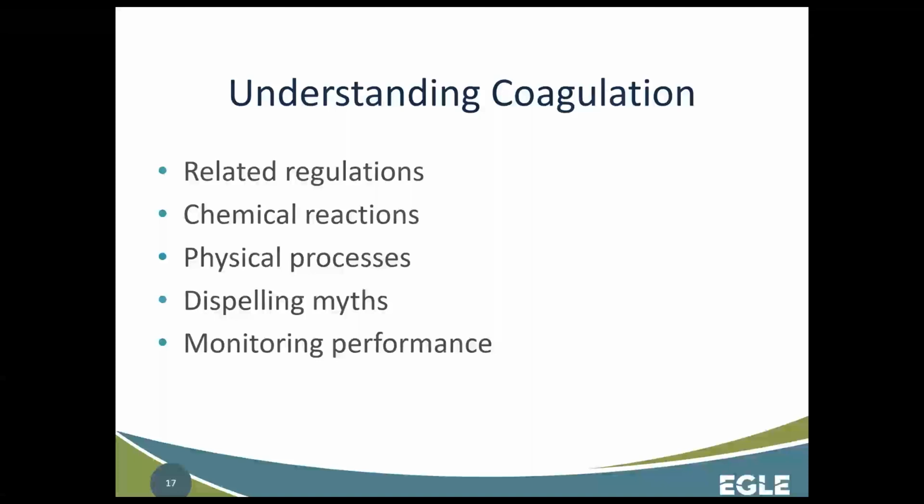Again, I never want to dismiss the ability of an operator to visually inspect a floc basin and to assess its performance. I think that's a very useful and very legitimate way to do it. But on the other hand, before coagulation, you can't see these particles. You have to rely on surrogate measurements like NTU or turbidity measurements. So there are some unique ways to monitor the performance, especially in the steps where visual observation doesn't really do you any good.